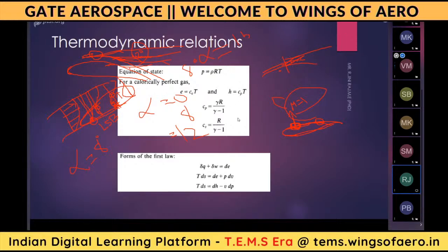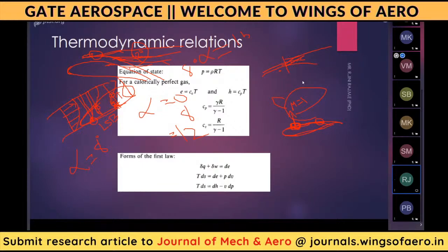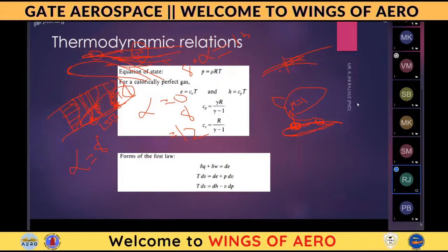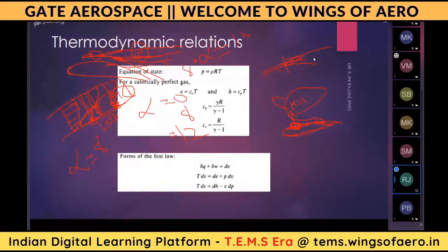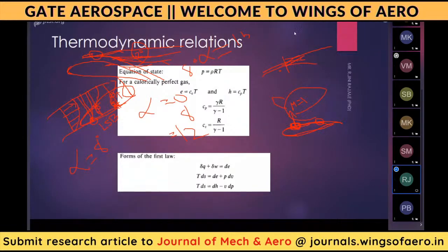Okay. Can the roughness of a surface be increased? No, if roughness increases, drag will automatically increase. You should not increase the roughness. Like, the flow must be attached to the surface for a longer period of time, sir. Yes, the flow should be attached for a longer period of time, but one more thing we should focus on, because here lift is also a concern and drag is also a concern. We need a maximum L by D ratio. Okay, the L by D ratio should be maximum.